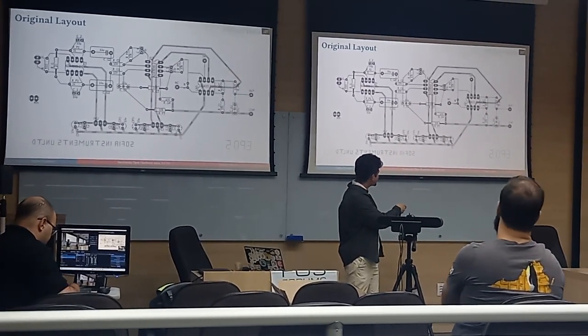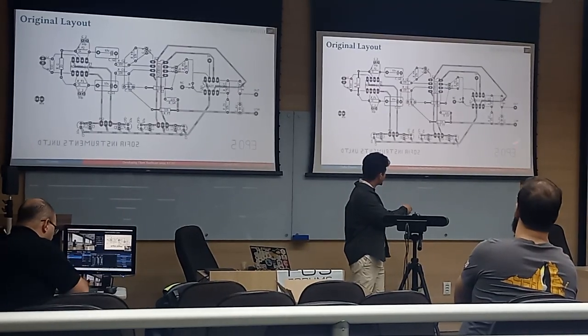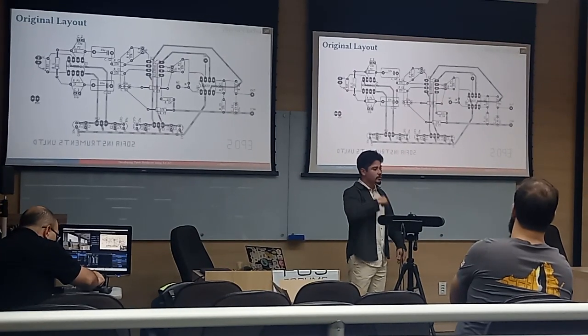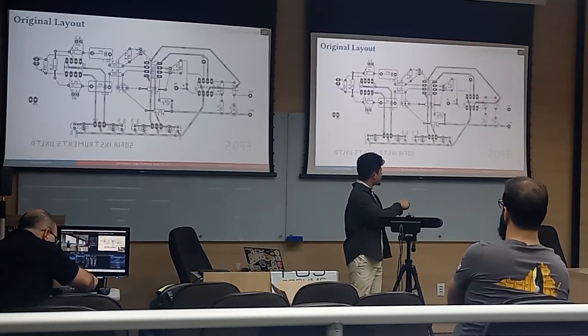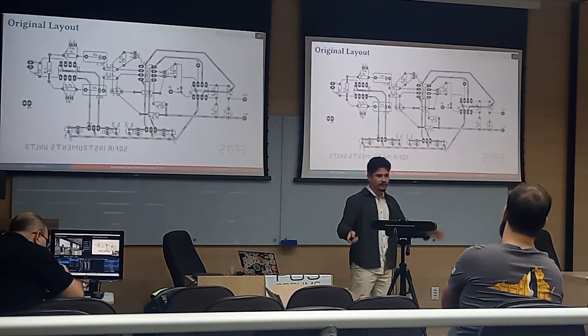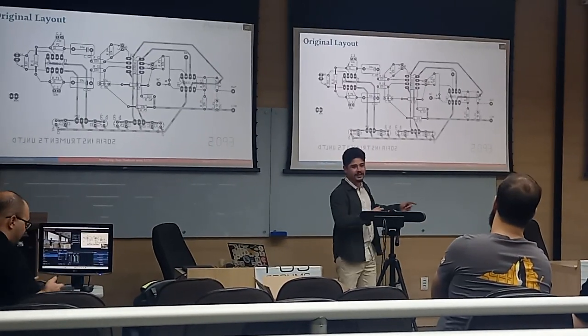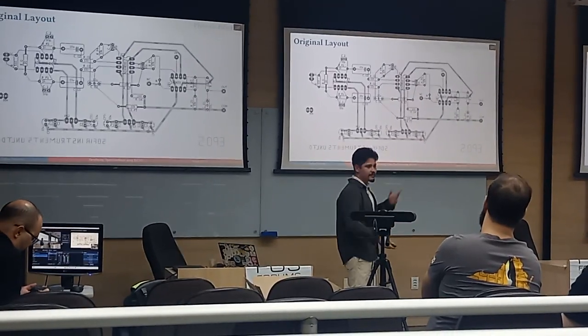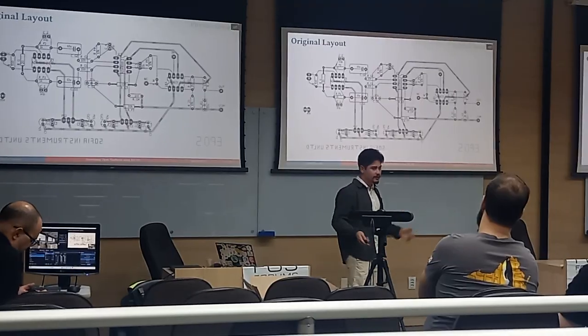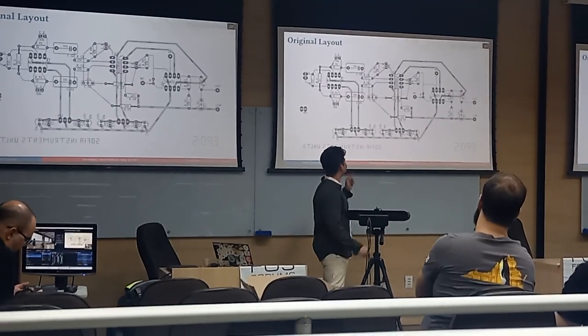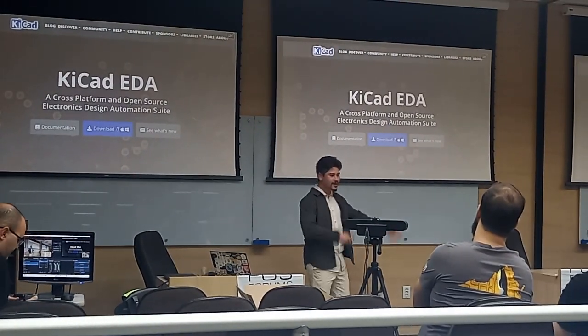And in this part of the circuit, this here just makes the square part, it's a voltage multiplier, and in the end, just a low pass filter, for the guys who didn't know electronics, this takes the average. So in the end, we measure the mean square voltage of the signal. With this, we can determine the Boltzmann constant. Okay, you guys understand the idea. So, okay, let's do the board.